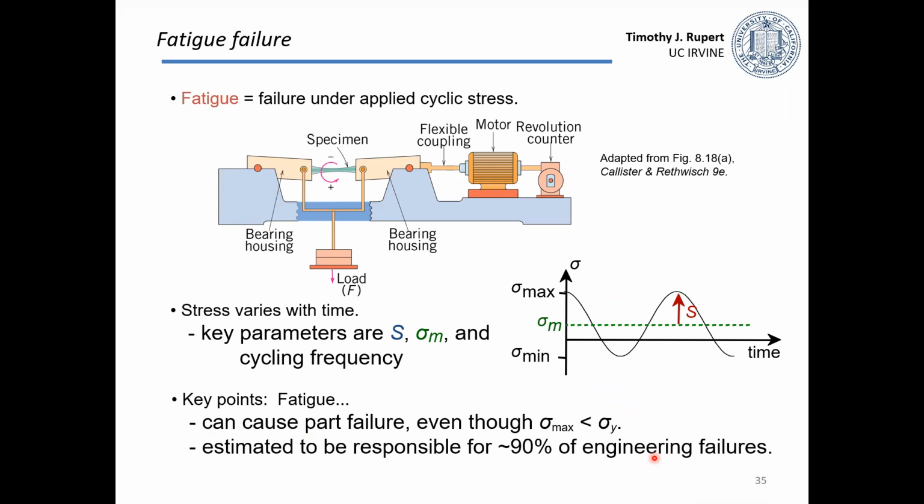Now, part of that has to do with how well we understand yielding. So if you design a material part and it fails through yielding the first time it's used, you're a very bad engineer. No, the sample's loaded up, keep it below its yield strength, okay? The issue with fatigue is it's a little bit harder to predict, right? So, and you're also talking about something happening over maybe years.